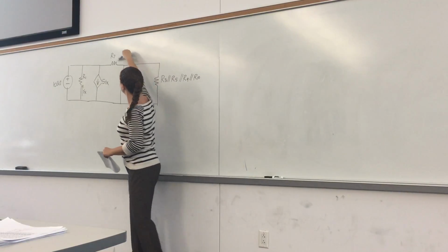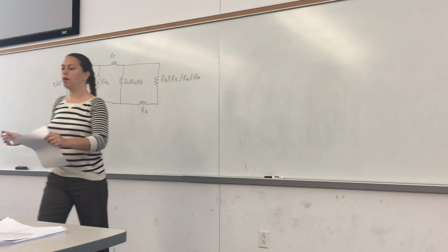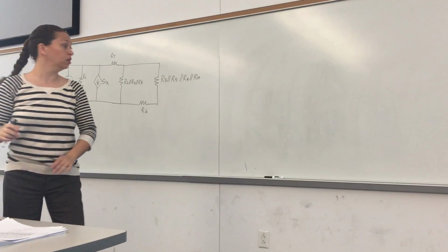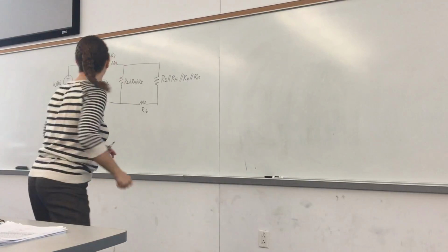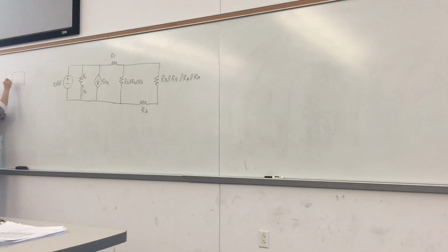That was kind of like making a loop around the same node, coming back. Now, as a general rule, when we have a circuit here, some kind of a circuit, and then there is this resistor, Rs, right? If you have a resistor like that, floating, no current through it, then that's going to be irrelevant to the solution. We're going to ignore those resistors.